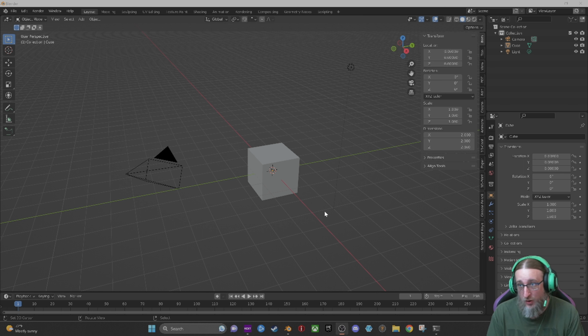So we're going to subdivide that by 30 and then I'm going to get all these little boxes. I'm going to right click outside of it just to get rid of the box and to apply that, because once you click anywhere else other than that box, you apply however many subdivisions you did. So you don't want to click outside of that box before you add the number of subdivisions. Otherwise, you can just hit W or hit A again and then hit W and do that whole process again without clicking on anything else.